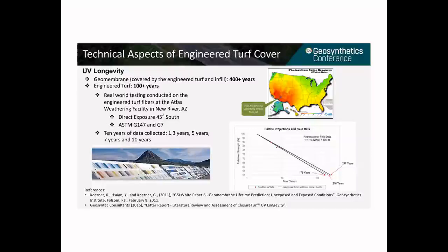Let's look at some technical aspects of the engineered turf cover. One of the most frequently asked questions is how long the engineered turf cover will last. As we know, geosynthetic materials are subject to UV degradation under sunlight. For the engineered turf cover, the geomembrane is covered by the engineered turf and infill and therefore protected from direct exposure to sunlight. Results of the extensive study by Geosynthetic Research Institute indicate that a covered geomembrane can last more